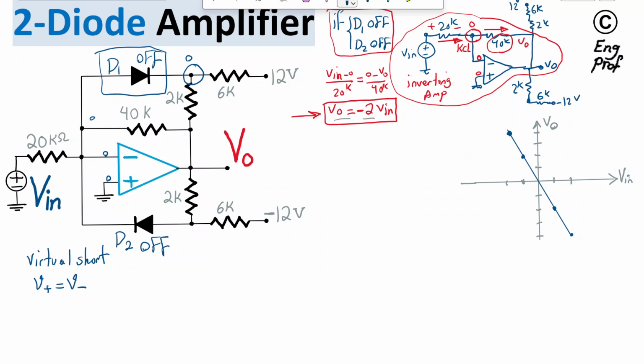So that is the voltage at, in this case, the left side of this diode. For this ideal diode to turn on, when it is off, the moment the right side of it gets to 0, that's the moment the diode starts turning on, because this requires a voltage drop like this. In practice it is 0.7 volt, but in this case, for an ideal diode, it just needs a barely positive voltage with this polarity across that diode.